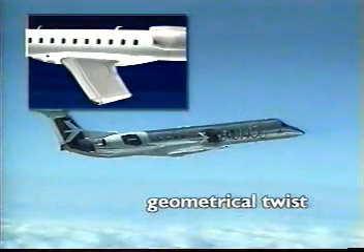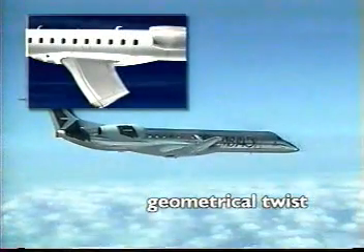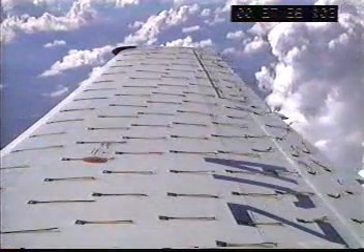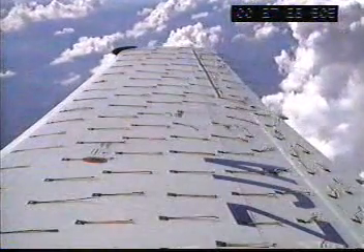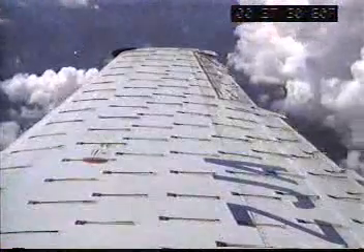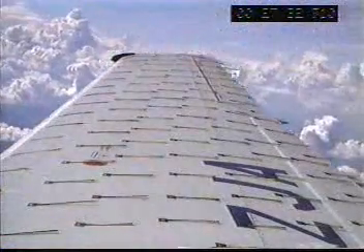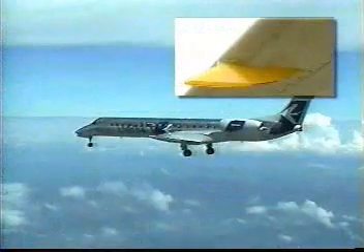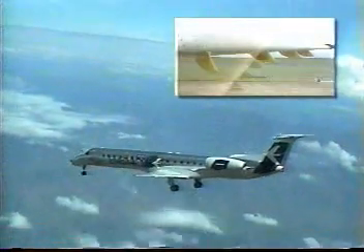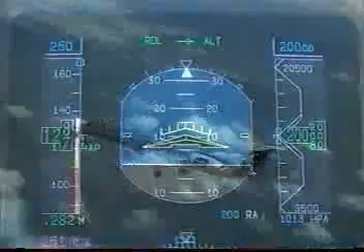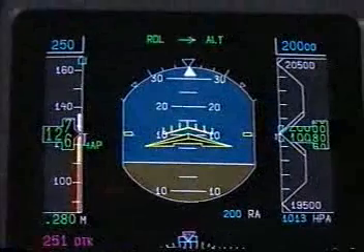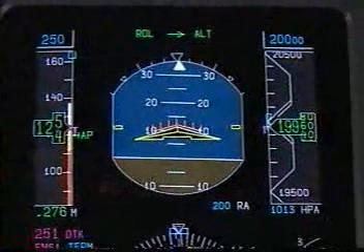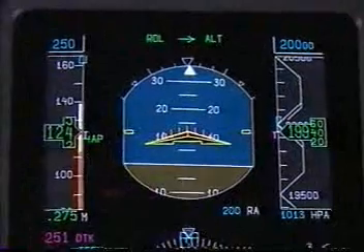The Embraer jets make use of wing geometrical twist to decrease the local angle of attack at the tip. In addition, the airfoil section is varied throughout the span to an airfoil with delayed stall development. Another feature used in the Embraer jet family are those interesting vortilons installed at the wing tip. They delay tip stall even more, so the jets have full roll control throughout the normal operating range down to stick pusher speeds.